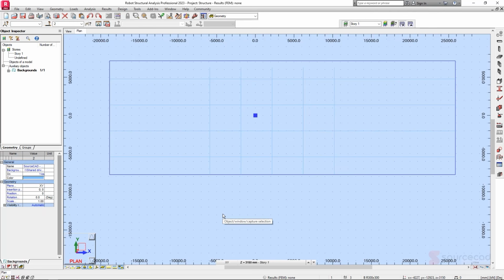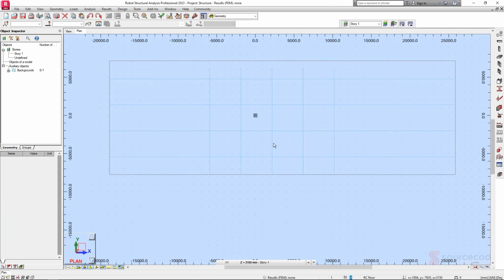So in this part 2, we'll be focusing on specifically setting our structure, creating our supports, applying our loads, creating our members. Then we're going to do our analysis parameters check, and then we're going to visualize the results as well as creating reports. So having said that, we have our grid. Now let's create our axis.